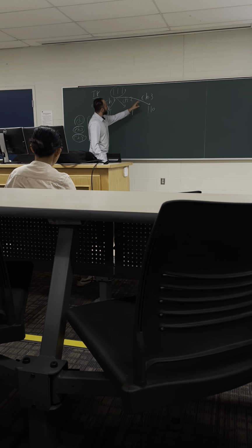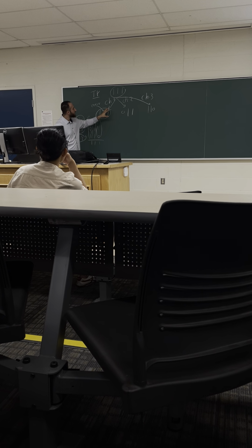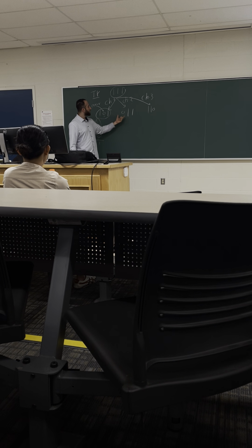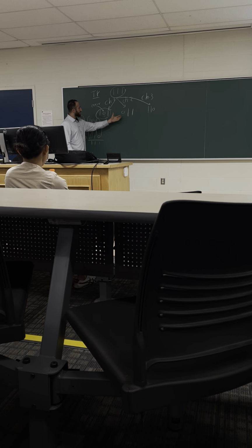And the second keyword is that you have independent channels, because if you send the same symbol over the same channel, you will obtain the same error, right? So you will obtain 101, and even if you send it 100 times, you receive 101. If you have majority vote, the majority vote will say 101, right? So you need to change the environment, which means you send it over an independent channel in order to obtain a different error. And this different environment will help you find the correct one, okay?